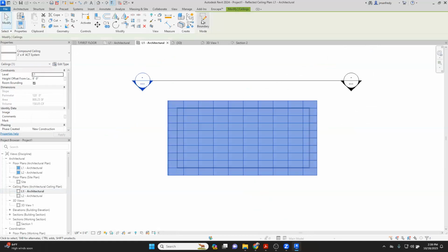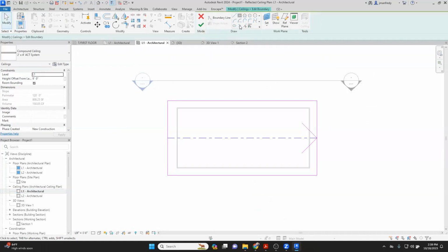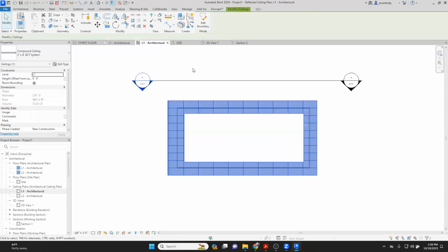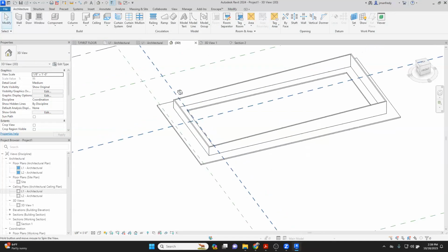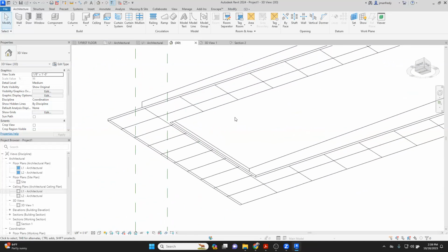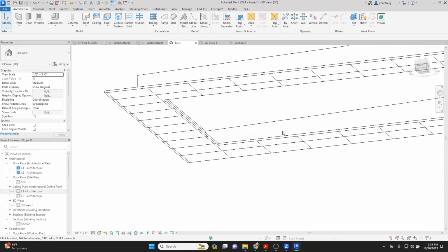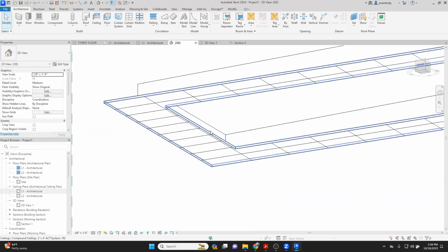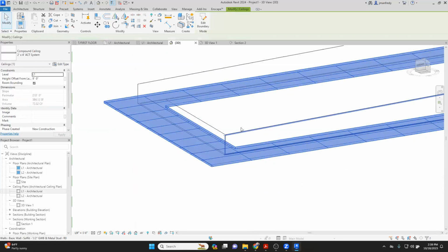All right, just take this ceiling and edit type and then just make an opening inside of it. And it makes maybe this is the light cove. Maybe I can see inside of here. And it shines up on that ceiling there. And there's glowing with light along these edges here. So you make an opening inside there.